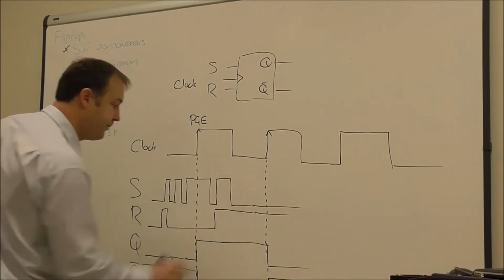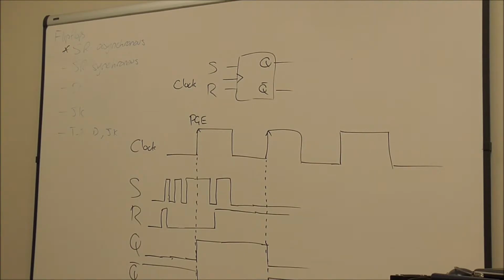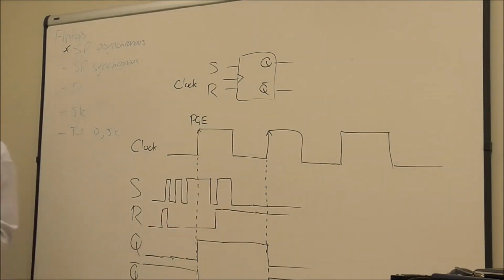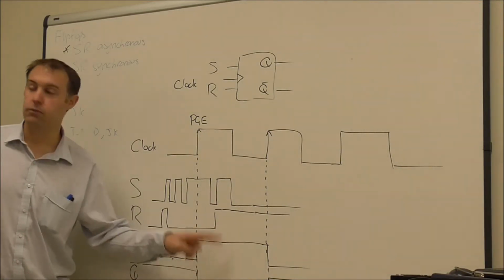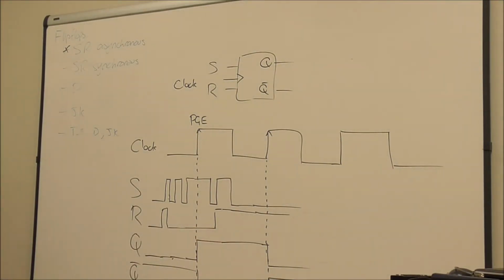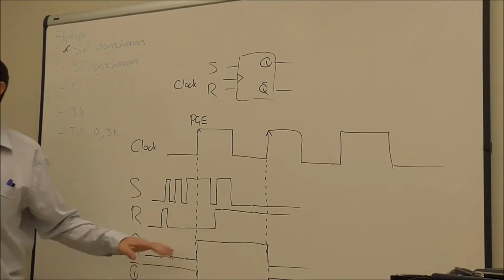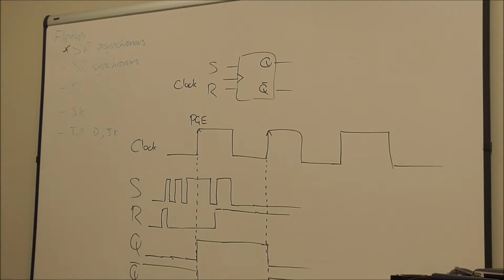So let's add one in. Why not? Okay, that wouldn't have been a problem in a synchronous circuit. If it was an asynchronous circuit, we might be seeing all sorts of rapid changes on the output there. And if that was driving some other logic, that could cause further problems. Okay? So for a synchronous circuit, the outputs change synchronized by the clock pin.